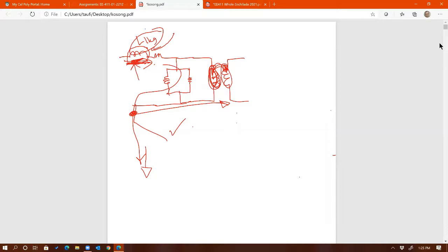Because this MOSFET, let's say, is only rated at 50 volts, and because this inductor refuses to stop its current, it will create voltage at this node that is larger than 50 volts. It could be 100 volts peak, right? That could damage this MOSFET. Remember, SOA for voltage is absolute, right?